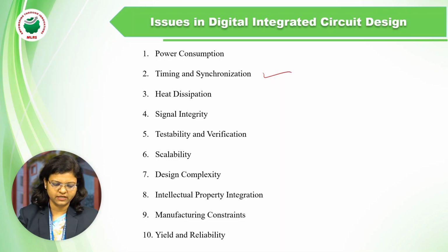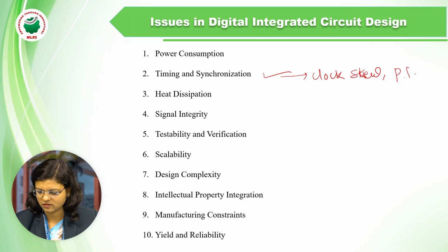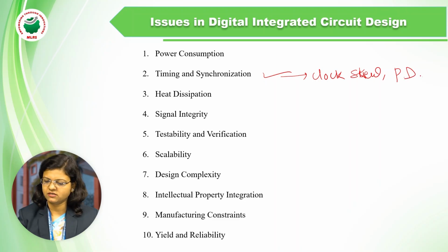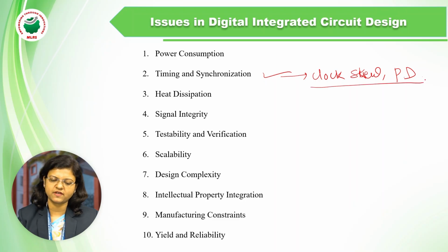There are some timing related challenges, for example clock skew, which is nothing but the difference in the arrival of the clock signals, and propagation delay, which is how the signal propagates from the input to the output or through the whole circuit. These are the issues we have to reduce in timing and synchronization.